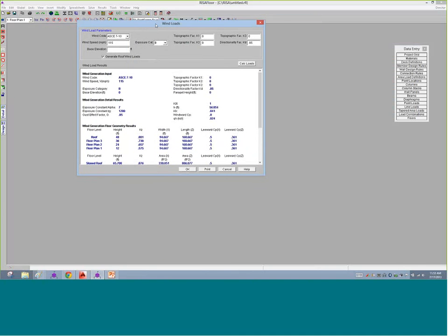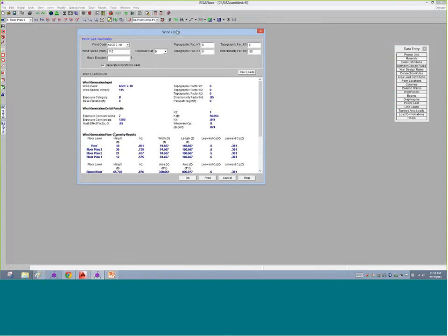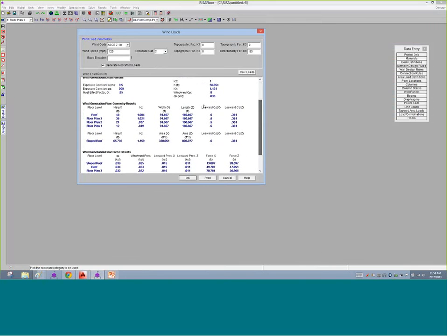Okay, so in RISA 3D, what we did, we took only the lateral elements, just those wood walls, the red elements, and we tell the program we're going to be calculating the wind and seismic here. There's a calculator, and these are automatically calculated for us. We tell the program 120 miles per hour, exposure category C. I can say calculate those loads. What I see in here is kind of an echo of all the information I just put in. It tells me some of the design parameters based on what I put into the program. And lastly, that qH there is going to be our kips per square foot. So we're seeing all that listed right there. That's the big number that gets calculated, and it goes per floor level.